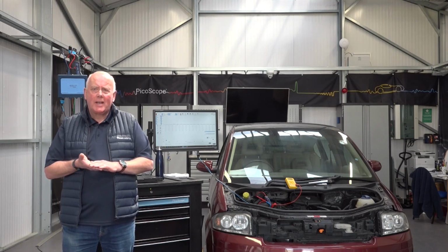The point is that we've got 4 million dots across the screen, and this is really where the voltmeter cannot cope. It's just averaging everything out. So we're looking at the on and off switching of the camshaft sensor and comparing it. Remember, save what you've got, and we're going to talk about the waveform library later. Thanks, John. Back to you.